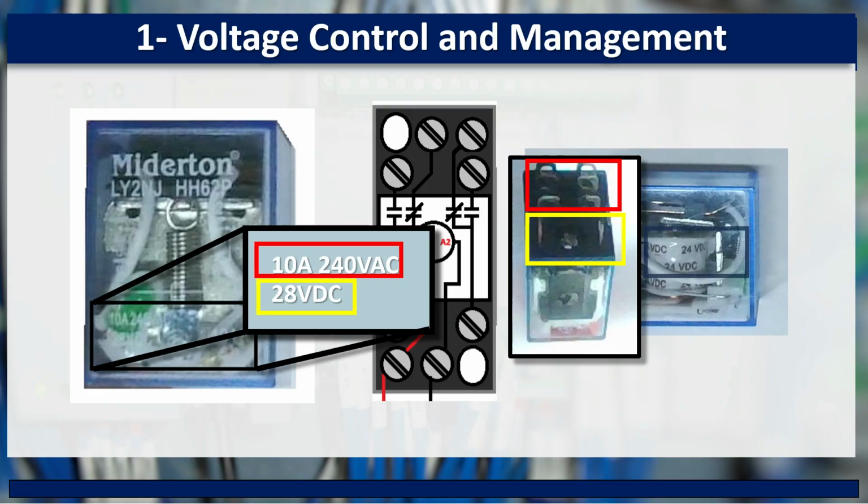The 240/250 VAC and 28 VDC markings are maximum contact switching voltage ratings. The coil is rated separately, in this case 24 VDC. However, these values do not mean the relay is suitable for every type of load at those limits. Always check the manufacturer's specifications for the proper application and the intended load and duty.